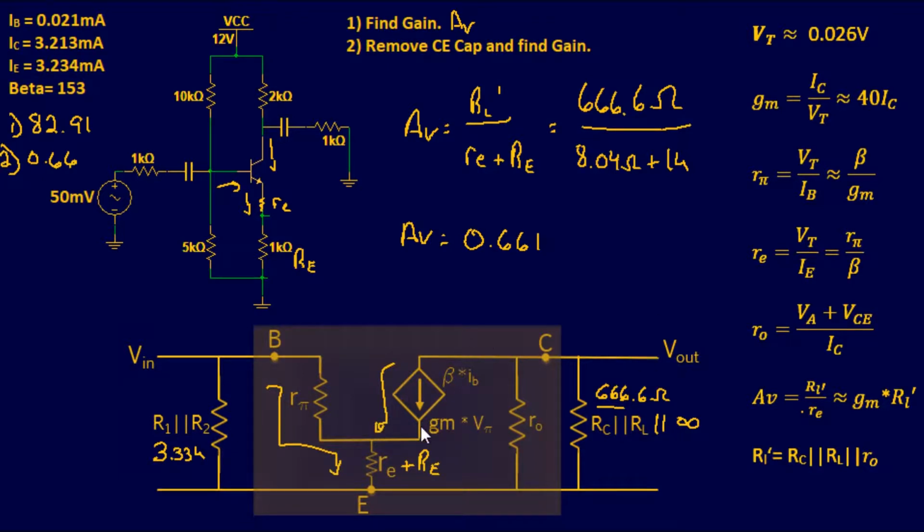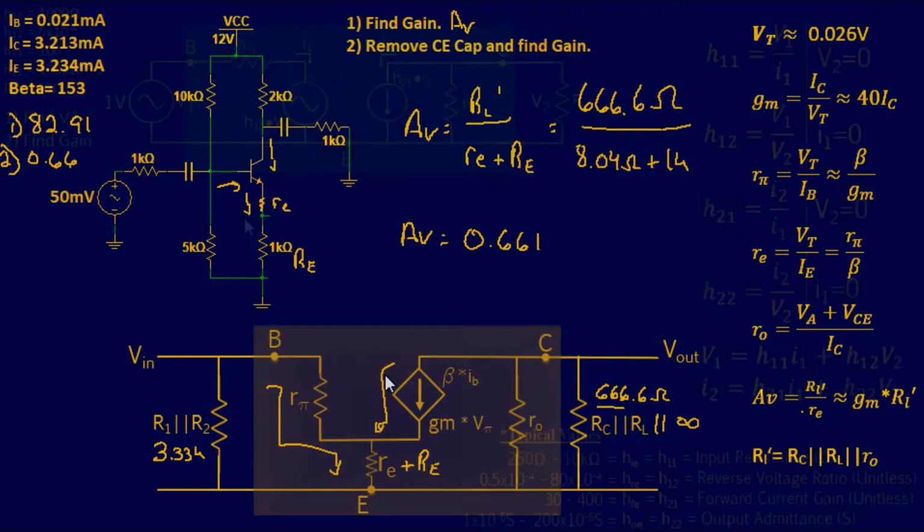Now you can visually see the current flow as far as the AC circuit analysis. So it's very similar to DC, however there's a few equation differences. Now that we have the voltage gain, you can actually put back the 50 millivolts with the 1 k ohm resistor and start finding out what the output voltage would really be, just based on now that you have a gain.